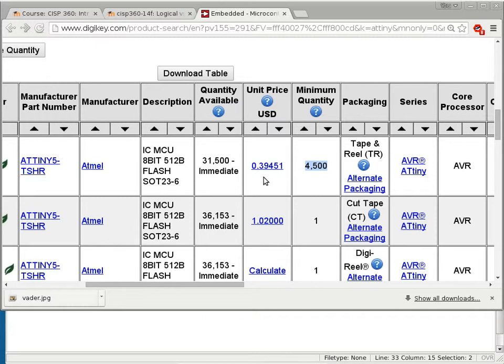If you take 4 dimes and walk into the bookstore, what can you buy? Exactly. 40 cents will get you a chip like this. Even though it looks really simple, it doesn't seem to do a whole lot. It has a processor in it. It has flash to store a program, and it has RAM for variables. It even has a built-in oscillator, so you don't need an external clock. For those of you who know what a clock is, it only takes 0, the ground, and also I think 3.3 volts to run, and then you can use it to control stuff.